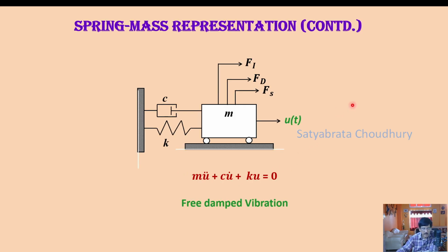Let us see now a damped case. In the damped case, along with the spring K, you have to show a damper here. This is called a dashpot. So imagine it is filled with fluid and this plate is moving within the fluid. So it creates a viscous damping inside the system. This is used in the shock absorbers of two-wheelers, three-wheelers and four-wheelers, and in many other appliances, the damping dashpot system is utilized.